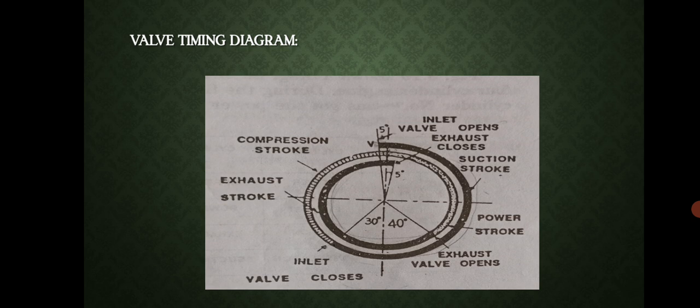Theoretically, the intake valve opens only at TDC and closes at BDC, whereas the exhaust valve should open at BDC and close at TDC. But in actual practice these angles differ.